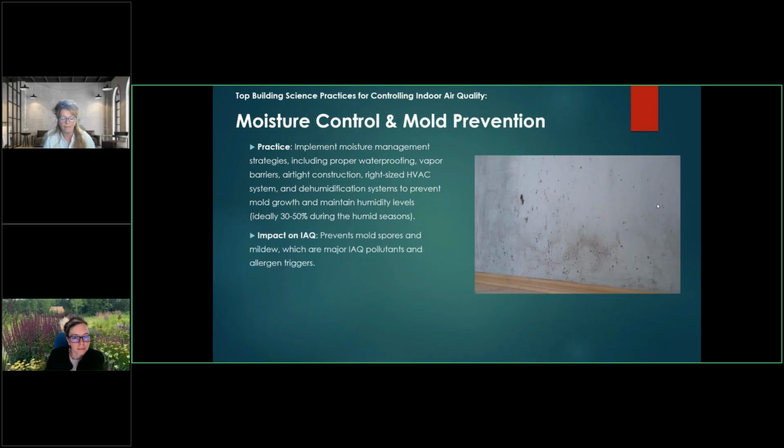So, obviously the ultimate goal is to prevent mold and mildew. But the reality is we have wetting and drying times of the year, and typically leakier homes didn't have as many mold and mildew issues because they would wet and dry and wet and dry. But now that we're having hot, tighter homes, we seem to be wetting a lot more.